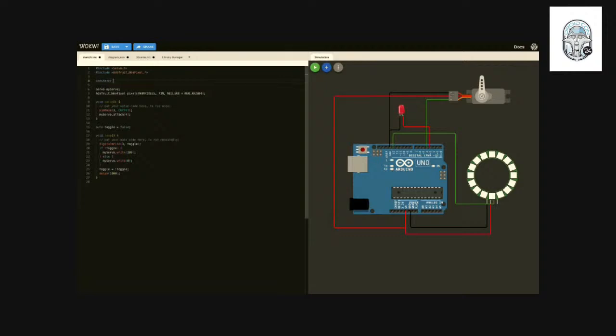One way is to use constexpr auto and say, for example, NUM_PIXELS is equal to 16. You'll also see something that says define. You'll see const int NUM_PIXELS. I prefer to use something like auto and constexpr. None of them is any righter than the other one. It's just a question of what you prefer.